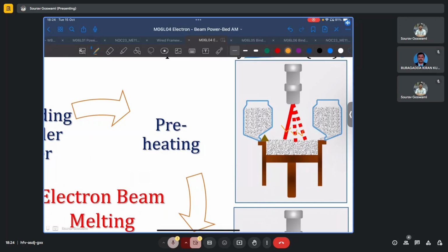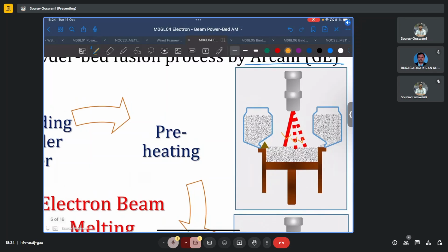Whereas if we were to do this with the same beam diameter without changing and just by reducing the power, the number of scans required would be more. Again, because this process is so fast, maybe in terms of time, the difference would not be so much. But typically, this is what is adopted. So either your beam dia can be increased or the beam can be defocused so that effectively the beam spot size on your target surface increases or gets enlarged.